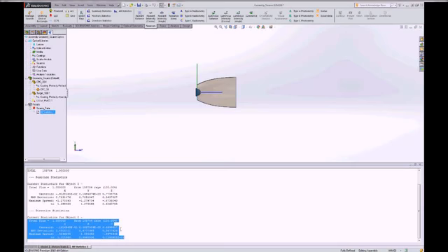And since this LED is nominally Lambertian, I would expect on average the light is directed along the axis and covering all of direction cosine space. Okay, half of it approximately with direction cosines less than 0.5, half with direction cosines greater than 0.5. So this looks like a reasonable representation.